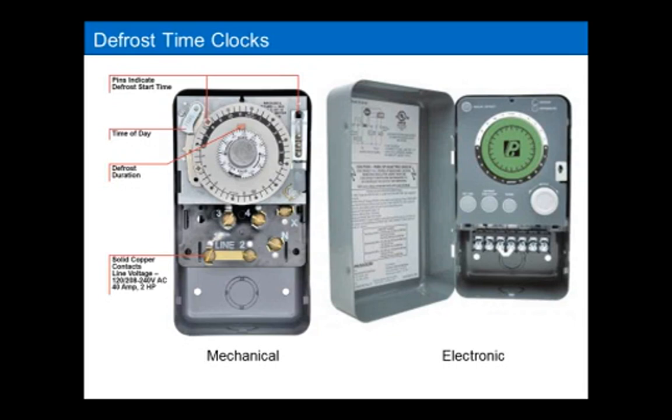If the box is being used a lot, where the door is being opened a lot, and you're bringing in this warm air each time the door is open, that warm humid air is going to eventually condense on the evaporator and have to be defrosted. So if it's a hot and humid environment and they're in and out of this cabinet regularly, you might have to go with several defrost cycles per day.